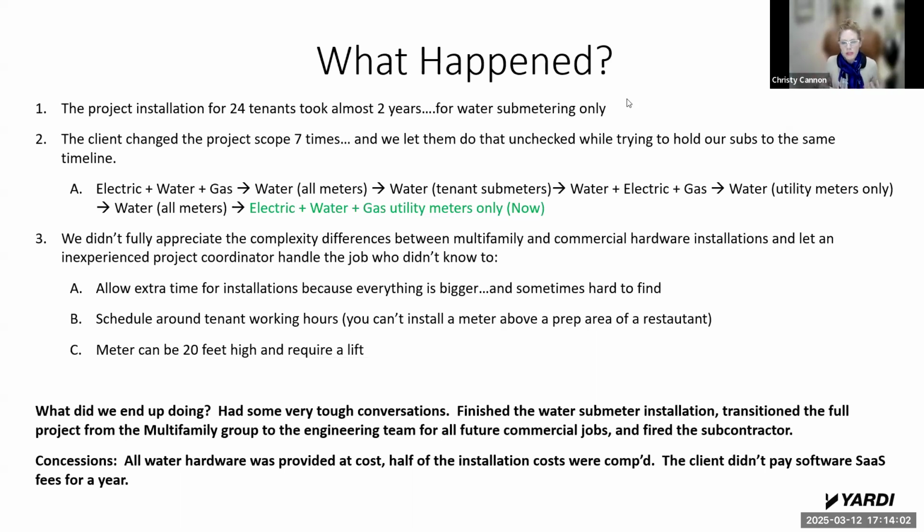The water meters are bigger, which means they might usually spec a little inline turbine water meter, but anything over 2 inches, you really don't want to do that because it's a maintenance headache. You really want to do something different, but they don't know that because they don't work a lot on commercial. The other thing too is it's different scheduling, site assessments, and installations around commercial tenant hours than it is multifamily resident unit visits. Completely different. And then sometimes there are things like lift required.